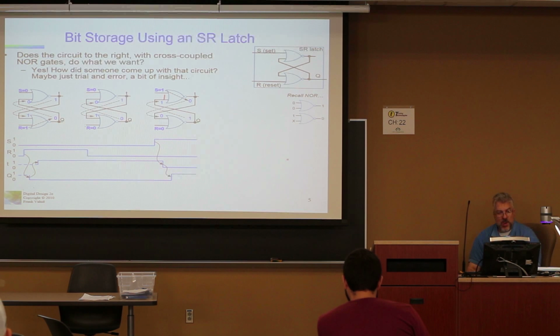So in other words, we have this set that actually creates an output on Q. And so very often the output of your sequential device is going to be the letter Q, and your input will be S. We'll also have another reset line going in. We're going to put this in a box, and we're going to call it a latch.